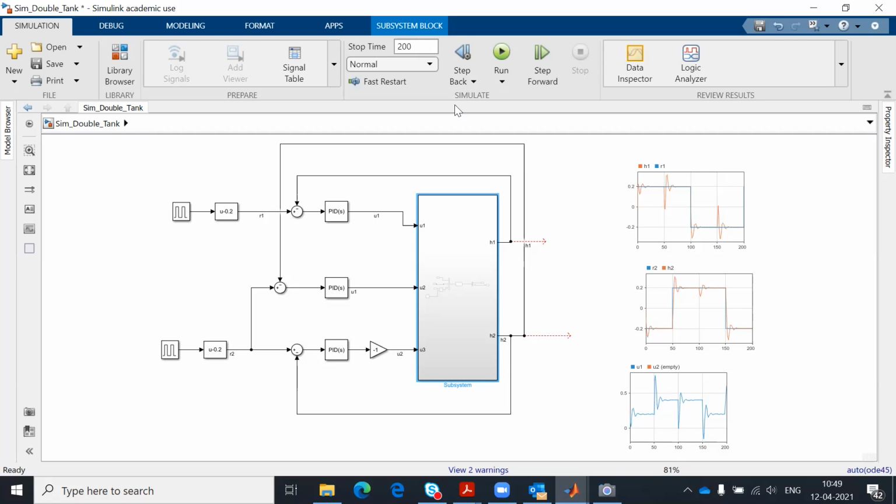It could be, for example, 100 kilograms, or it could be 10 tons. The controller you design for the crane from one load to another could be different, because if you use the same controller for all loads, you can design a controller that works for all loads, but the performance is not high because you need to design a robust controller that works for all of them. Therefore, the controller is conservative. Okay, so I'm explaining the difference between fault tolerant control and robust control.